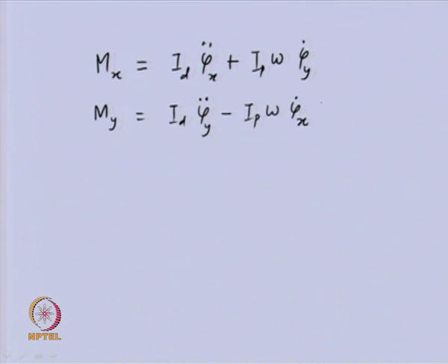Basically, if you see, this equation is similar to Newton's law, in which we equate the sum of all the external forces acting on the disc to the inertia term. Both are inertia terms. One comes from the diametral mass moment of inertia of the disc, another from the polar mass moment of inertia of the disc, and while obtaining the equation of motion, we need to consider these two inertia terms.